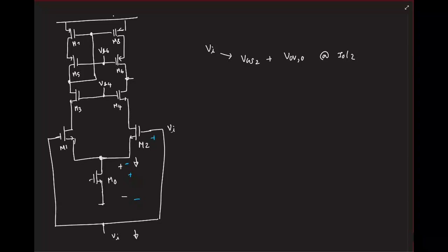Okay, great. So now let us say I keep increasing Vi. Which of these transistors will start to enter triode region? M1 and M2 at least makes sense. I am just changing the gate voltage of this, so better, these guys only be affected by that. And if I call this drain voltage as VD2, what is the maximum Vi can go?